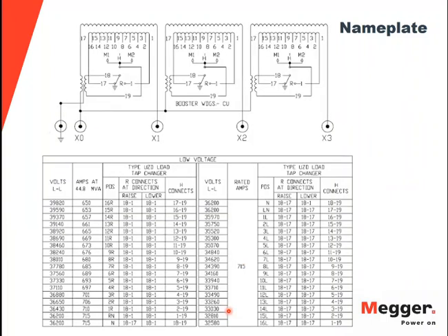In North America, it's very common to have a de-energized tap changer on the high side or primary side and on-load tap changer on the secondary side. You can run into different designs of on-load tap changer. The example that I have right here, you can see that I have a regulating winding that would get connected in series with the main winding, and as you can see that it has 16 tap positions and a reversing switch.